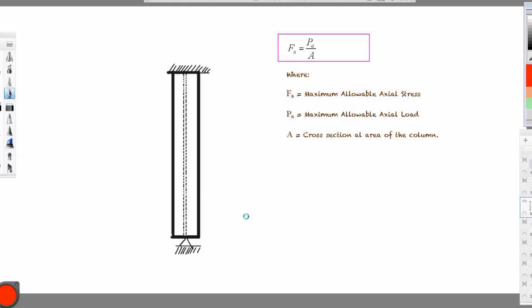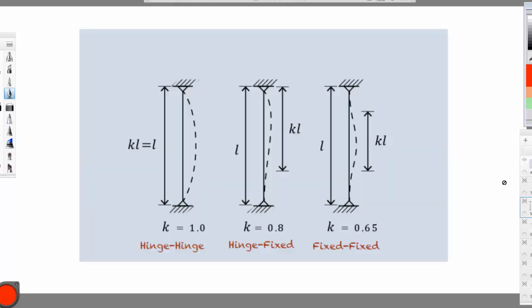To demonstrate the pattern of buckling, we have these three categories, which will be the main ones that we'll cover in this course. There are more than these categories, but we'll cover only these three. So you see in the case of hinge, this one, the column will buckle in this way. Meaning it will buckle through the entire height, so from here to here.